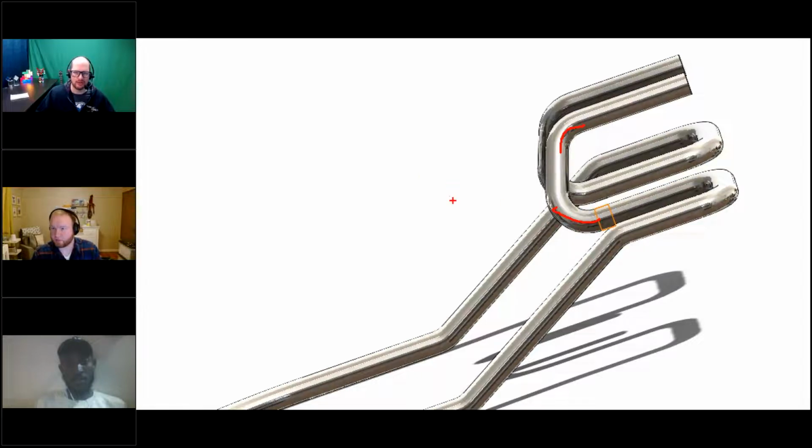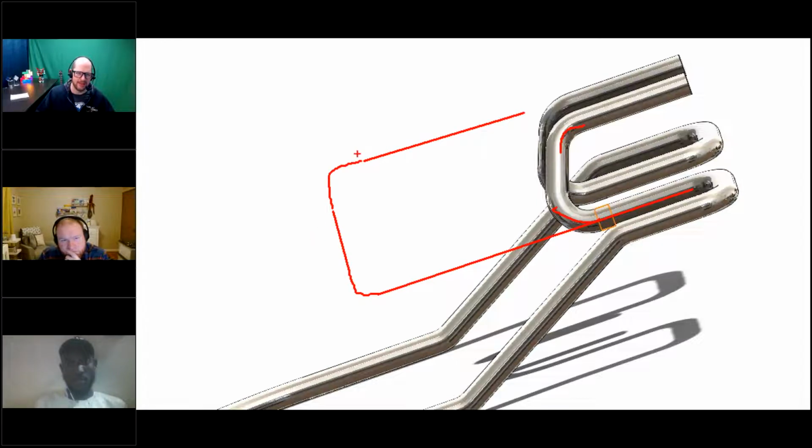You know, when you're in just straight 3D sketch mode, if you try to bring that out to be that longer version where you've got that tangency and then you've got the tangency here, in 3D sketch mode a lot of times that has a tendency to invert, where you end up with something more like this. And it can be very frustrating when those types of things happen.